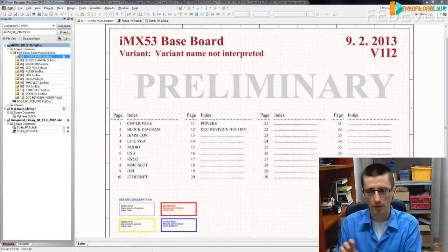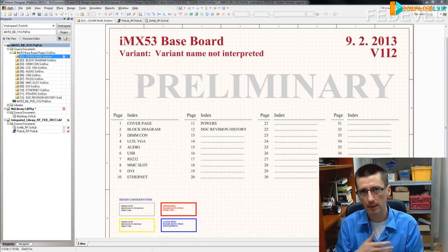If the component is too big and you can't fit your board into the enclosure, you have to redesign the board. It is almost the same as making an electrical mistake. You cannot use the board. So it's really important to see how the board will look.